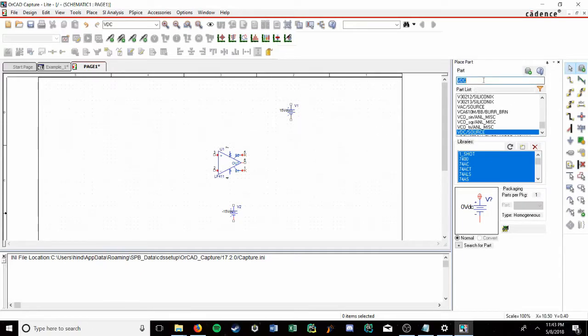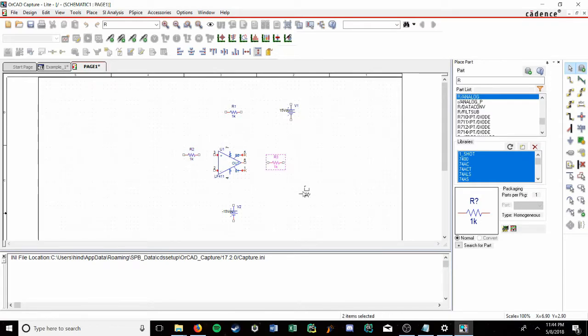From there, we'll want to put our resistors in. So just type in R, a lowercase r or a capital R. Do not type in resistor, because you'll get this model here, which will do weird things and your circuit won't run properly. So just push R and use the analog model. We want a resistor here, another resistor here, and I like to put a resistor for the load, though you don't have to.